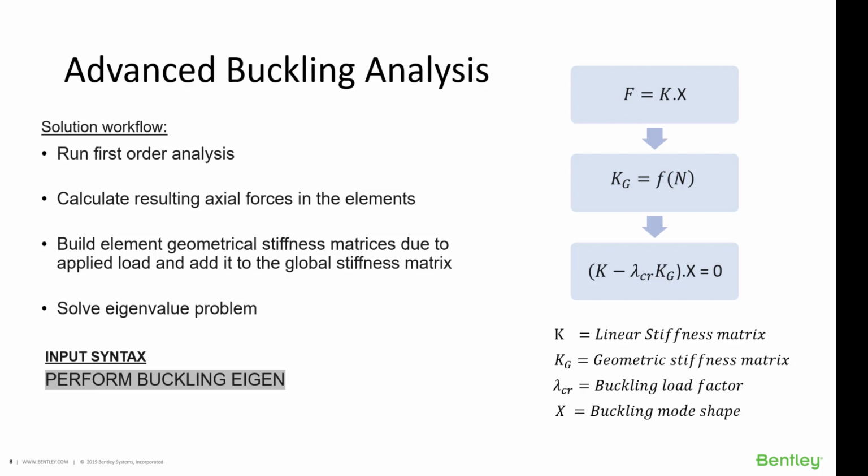These forces and stresses are used to calculate geometric stiffness terms. Both the large delta effects and the small delta effects for members are calculated. These terms are the terms of the geometric stiffness Kg matrix. Next, an eigenvalue problem is formed.